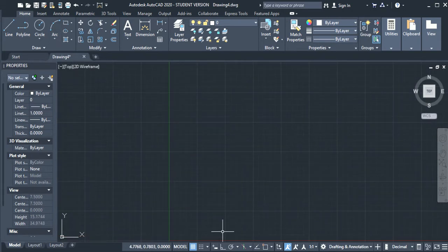To get started, let's turn on our snap mode and let's turn on our Ortho Snap cursor to 2D reference points. I'll show you what that does. Lastly, we're going to want to restrict cursor orthogonally, and we're going to turn that on. What that does is, let's say I have a line, it locks me to 0, 90, 180, or 270 degrees. It locks me in these positions.